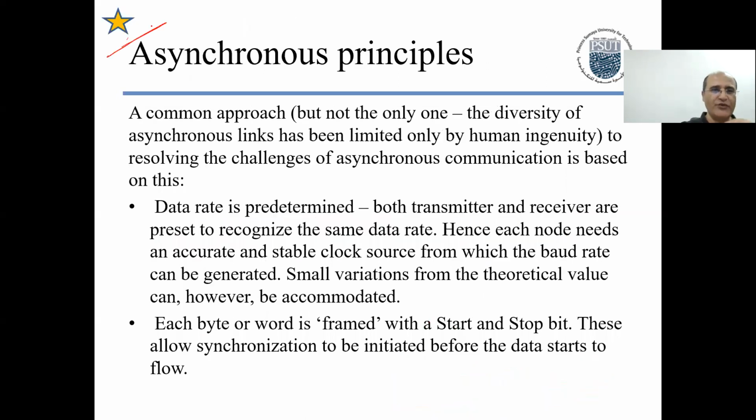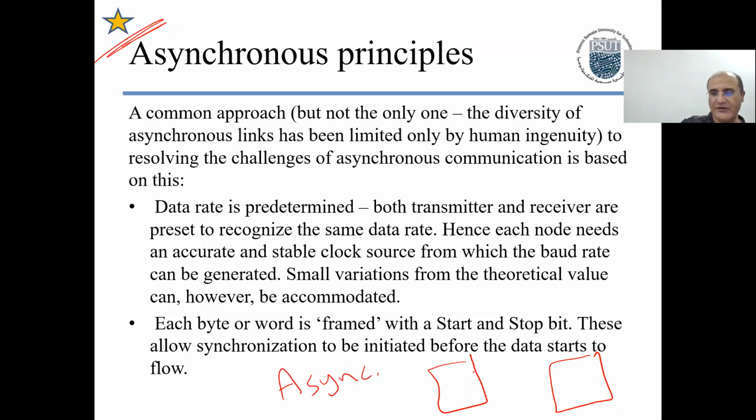So I put a star for you here. This is what I'm going to concentrate on, the asynchronous serial communication. When two devices want to communicate with each other using asynchronous serial communication, you have a transmit pin, you connect it with the receive pin on the other side, and a receive pin, you connect it with the transmit on the other side. That's it. You don't need a clock.